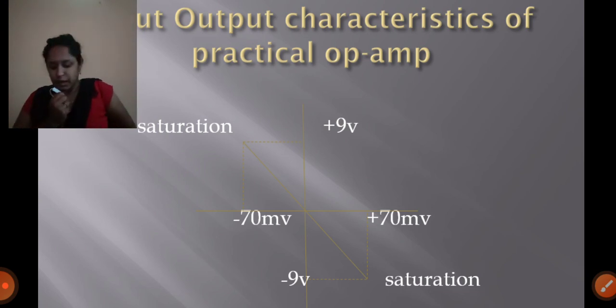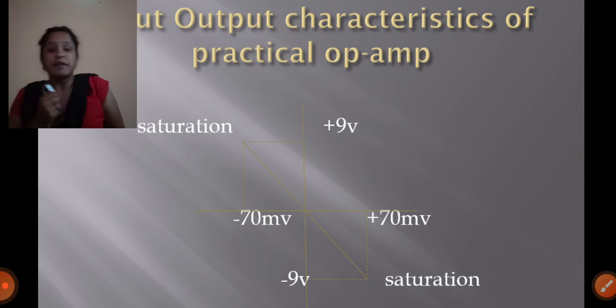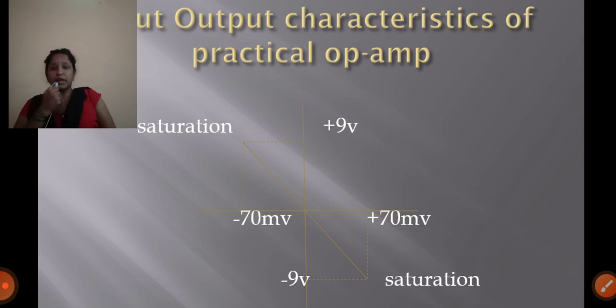We are using a DC power supply for the operational amplifier, though we can use both AC and DC. With the DC power supply, most output voltage excursions are limited within plus VCC and minus VEE, and similarly the output current from the operational amplifiers is also limited.